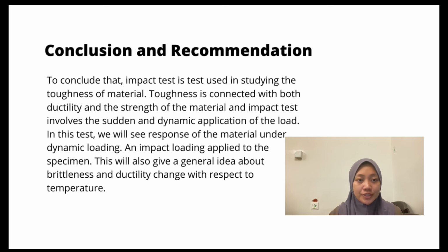Conclusion and recommendation. To conclude, the impact test is a test used in studying the toughness of material. Toughness is connected with both ductility and the strength of the material, and the impact test involves the sudden and dynamic application of the load. In this test, we will see the response of the material under dynamic loading and impact loading applied to the specimen. This will also give a general idea about how brittleness and ductility change with respect to temperature.